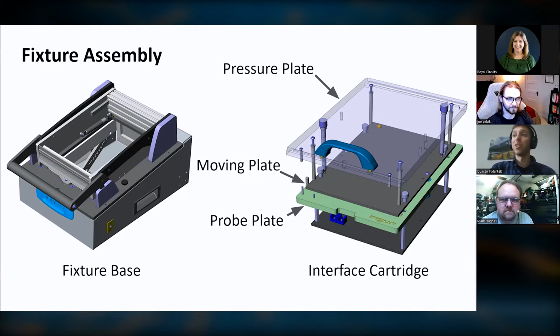Those are the files we want to start supporting on our platform, because they will give us all the test point locations and what the voltages are supposed to be at various locations. Whereas with Gerbers, it's just a vector file for the most part. It's fairly dumb. You don't know what net is what. So going to those newer file formats is going to be really interesting.